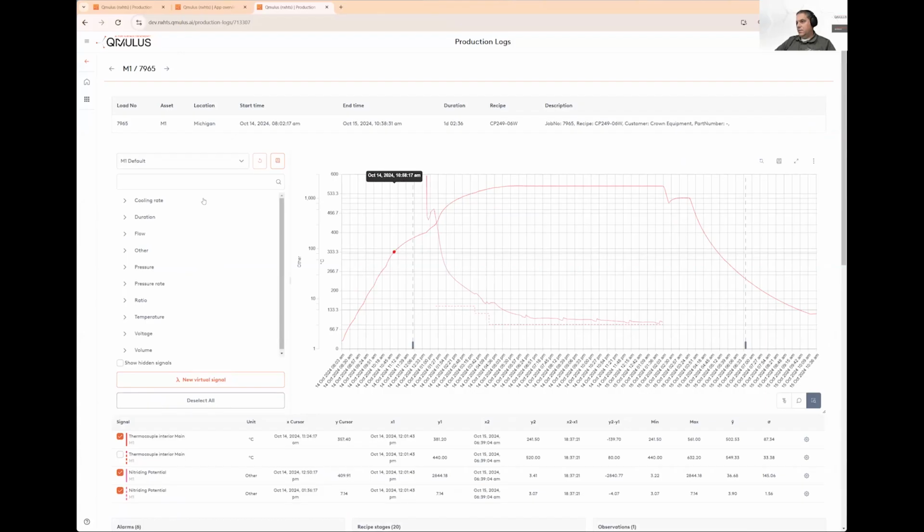I get to see now by default a temperature and a KN and its set point. I see that my interaction with the KN was not nice. I have these little bumps here. I don't like them, right? But not so bad. If I look at my KN, I have 3.5 instead of 3.07, 3.46 instead of 3.07, and not too worried, okay? Machine, I don't like the way it behaves, but now let's do something.